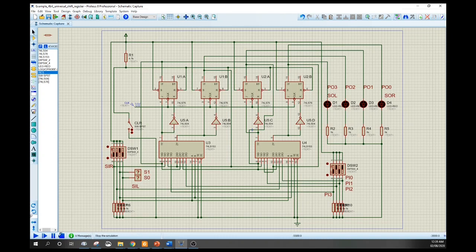So just to briefly show you the operation. Let's clear our circuit. And let's see, mode is 0, 0. Then this is no change. If we have here a 0, 1, then we shift to the right. So let's use the shift input. You can clearly see that 1 is being shifted into the shift register. If we bring SIR to 0, then we are shifting zeros.